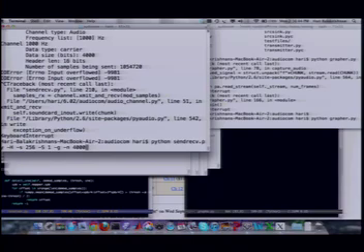The -S1 means that we send, capital S is the kind of source. It's something about the nature of the source. Capital S1 means that my entire information is sent as ones, which means I'm sending a pure sinusoidal carrier. All I'm doing is sending the sinusoidal carrier. Dash G just means show me some graphs, and N refers to the number of bits I wish to send. Okay? So these are all documented, and you don't have to worry about it.